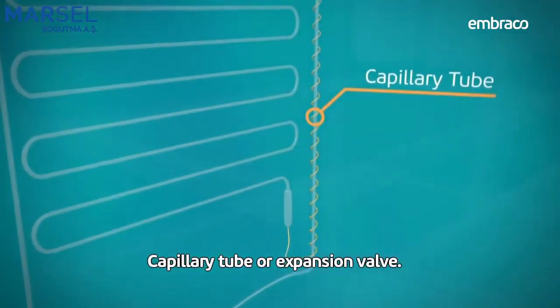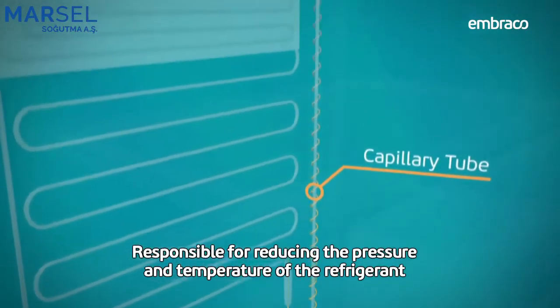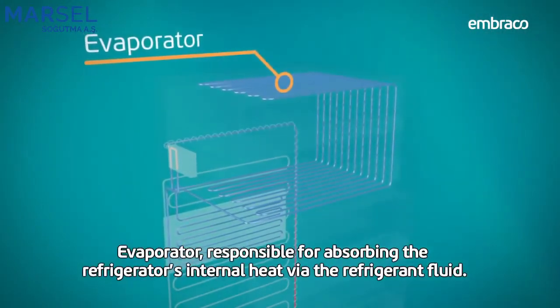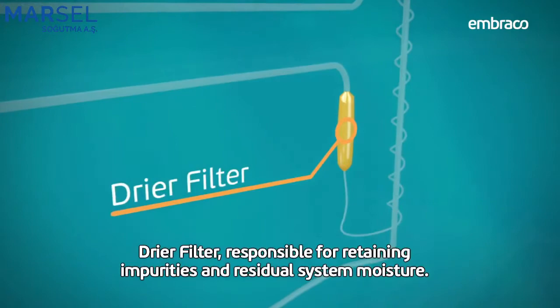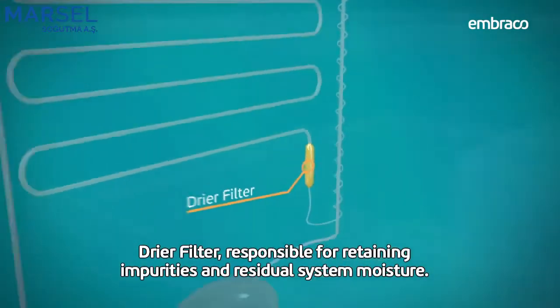Capillary tube or expansion valve, responsible for reducing the pressure and temperature of the refrigerant and metering it in the correct amount to the evaporator. Evaporator, responsible for absorbing the refrigerator's internal heat via the refrigerant fluid. Dryer filter, responsible for retaining impurities and residual system moisture.